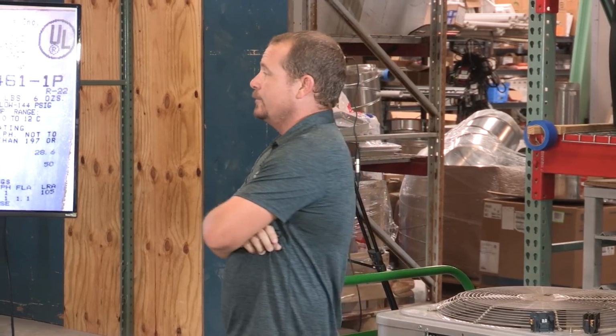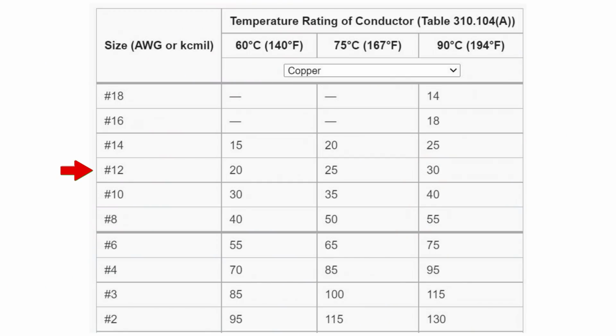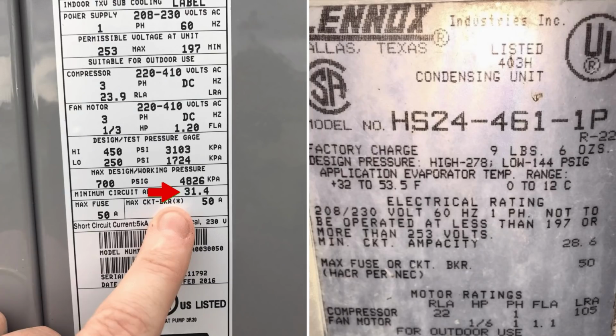And so if you have a conductor that is a number 12, if you're going to use the first column, number 12 copper, that means that the circuit breaker has to be what? A 20. That's what they'll say. Because you don't want to run the risk of it having an overcurrent condition and not tripping the breaker, melting the wire, right? Let's take a look here.